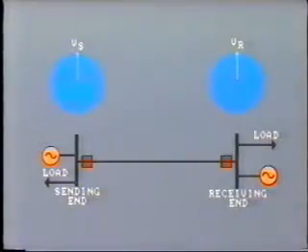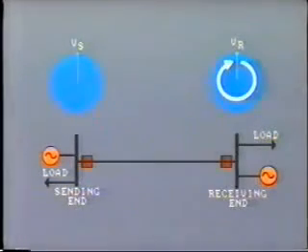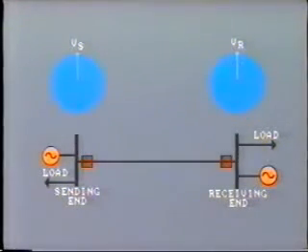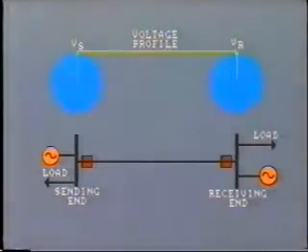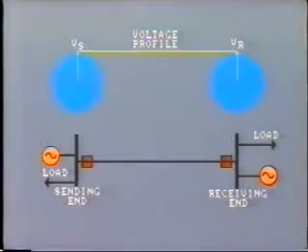Looking at a specific case, this transmission line has the sending end voltage fixed, with the receiving end voltage allowed to rotate. VR is equal to Vs. Under an out-of-step condition, the locus of VR is a circle. Let's look at the voltage level along the transmission line, where the sending end voltage and the receiving end voltage are both in phase, that is, with no power transfer.